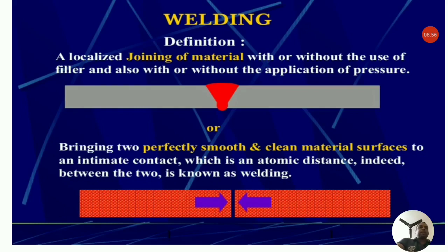Now welding, by contrast to the above, is a fabrication technique that is a metallurgical fusion process where the parent metal is melted. Here, the interface of the two parts to be joined is brought to a temperature above the melting point and then allowed to solidify so that a permanent joining takes place.